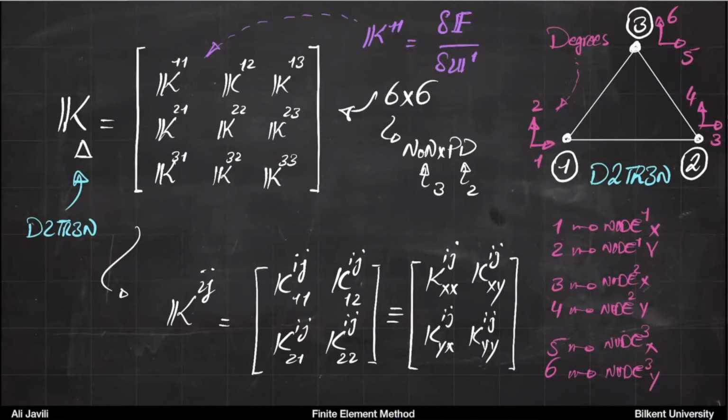And now you can clearly see that the force at node 1 has 2 directions. It's a vector. The displacement at node 1 also has 2 directions. So it's a vector. So for each of these components, you would have one particular component to that box. So basically that Kij or K11 itself has 4 components. Okay, in XX direction, XY direction, YX direction, and YY direction.